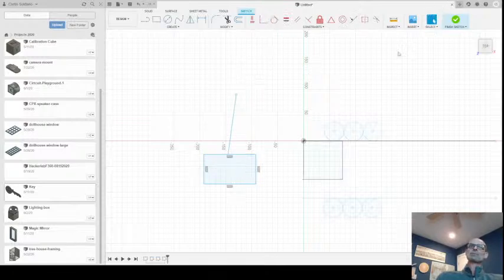And then I'm thinking, well, man, that looks a little off. Maybe I want to change it a little bit. So I'm trying to pull it over here and over here. But you'll notice when I get it exactly vertical, it actually shows me the constraint icon. So if I let go right now, it applies that constraint automatically. And now, even though I can still move this line back and forth on that ray, I cannot change the angle. So before, moving this dot would change the angle as it was attached to the line.